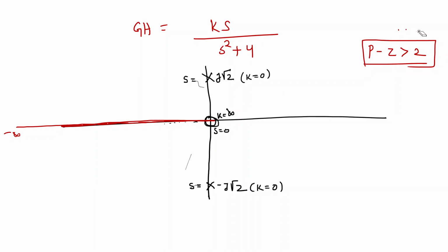This is what I'm calculating now: the centroid. Okay, this is the centroid condition. So the centroid is not required, but a breakpoint is required, ma'am. Why? Because we apply the third rule. Whenever a zero is there, and to the left of that zero there exists a root locus branch up to infinity, there is at least one breaking point when the number of poles is greater than the number of zeros. Getting my point? Apply the third rule.